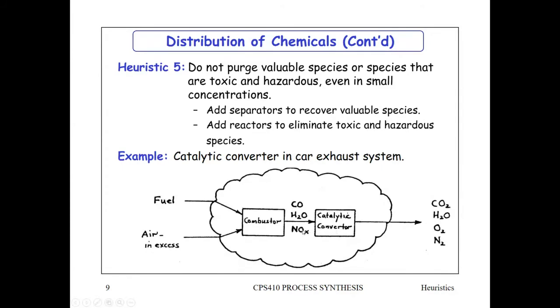And so the catalytic converter will convert the NOx gases into oxygen and nitrogen, and the CO into CO2 because there's excess oxygen available. So yeah, that's the purpose of a catalytic converter. It uses platinum in a honeycomb nanostructure. Well, it's maybe not nano. In a honeycomb type of structure, and that will convert all of these poisonous gases, CO and the NOx, and make harmless species.